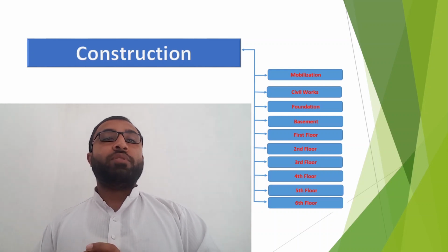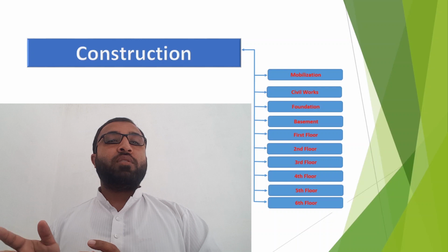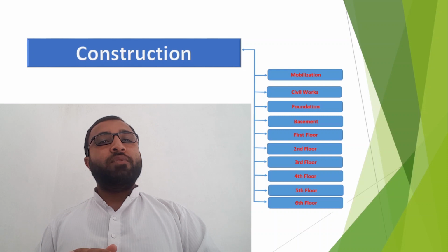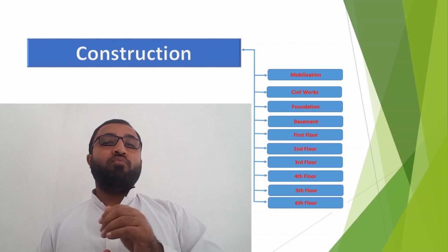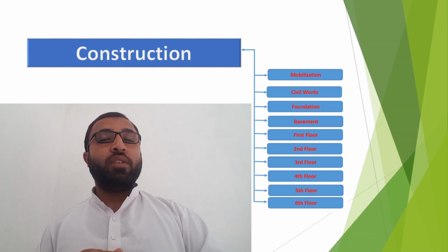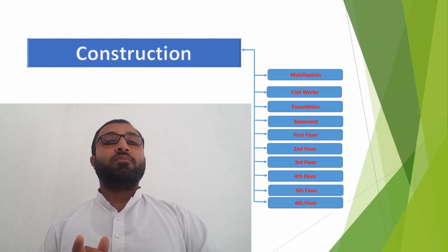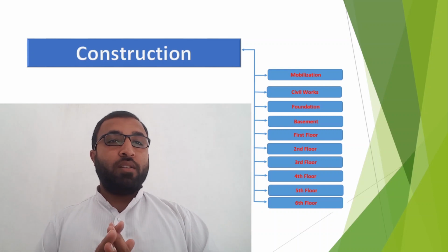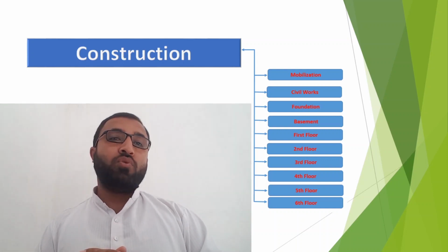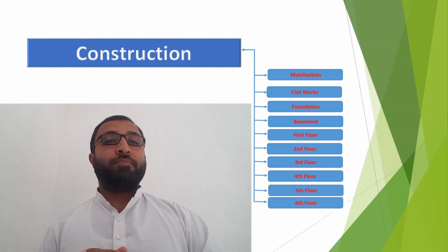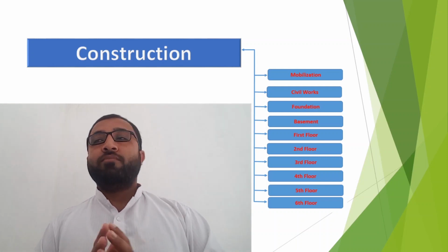So what we will do, we will start the rebar work in zone 1, and then we will wait, we will not start zone 2. After finishing the rebar work in zone 1, we will move to zone 2, and then the carpenters will come into zone 1 and start their shuttering. Meanwhile, we will be doing our rebar works in zone 2 in parallel. In zone 1 the carpenters are working, in zone 2 the steel fixers are working, so we can engage both crews at the same time to save time and to save our resources. So this we will see later on.